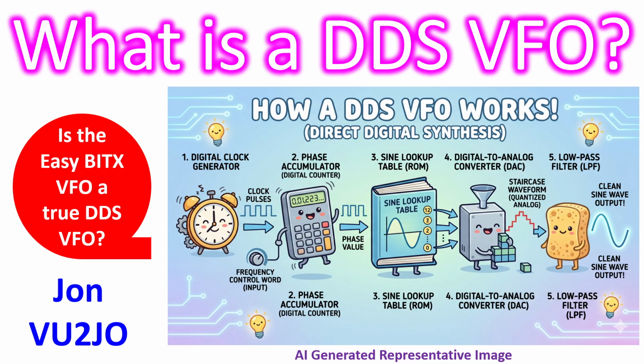Though I have been mentioning the VFO in my ECBTX build as a DDS VFO, in the strict sense it is not. Technically, it uses a PLL, phase locked loop clock generator, specifically the Silicon Labs SI5351A integrated circuit.